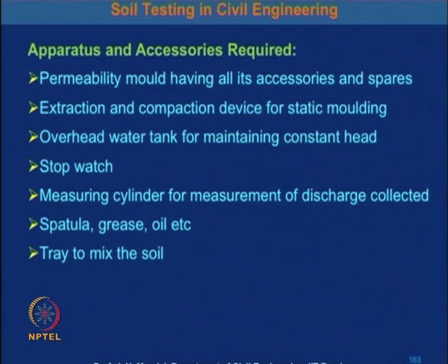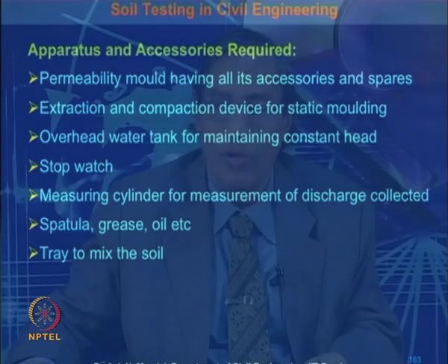Overhead water tank for maintaining the constant head. Stopwatch. Measuring cylinder for measurement of discharge collected. Spatula, grease, oil, etc. Tray to mix the soil.